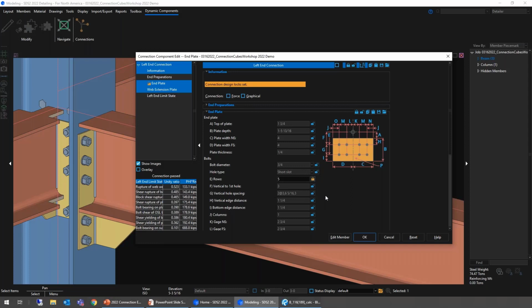The vertical hole spacing, you'll notice, uses variable spacing. That's to kind of clear that bottom flange. If we were looking at a clip angle connection, we'd have to cut the flange flush on both sides and everything so that our clip angle can clear that and extend down. So in this case, since we don't have to do all that in order to clear that bottom flange, we can use the variable hole spacing in there. You see we got 2 spaces at 3 inches, and then we got one at 6, and then 6 and 5/16, and then another one at 3. And you can override that just like anything else. So if I were to go 3 in there, might be a little tight on my bolt clearances there, but I can override that and get some different results there.